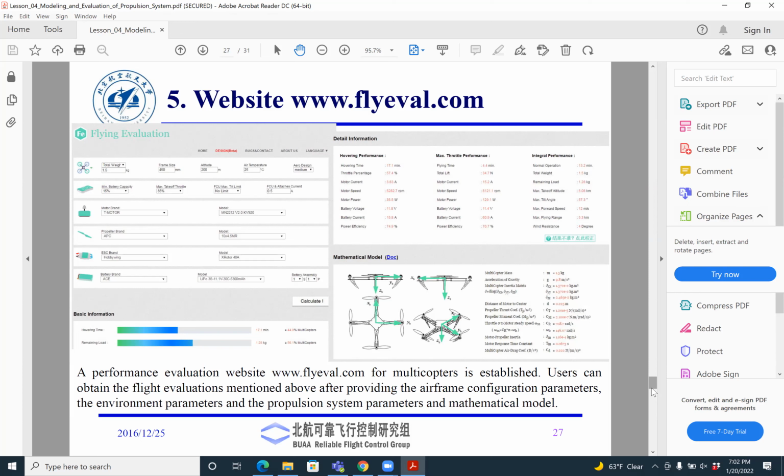There is an issue called the sling load. For example, if you have a load that is rigidly attached to the quadcopter frame, lifting that is easy. But if you have a load that is suspended from the quadcopter, lifting that is going to give you a load and a moment. The regular helicopter pilots that carry patients from one hospital to another are typically not certified to carry sling loads.